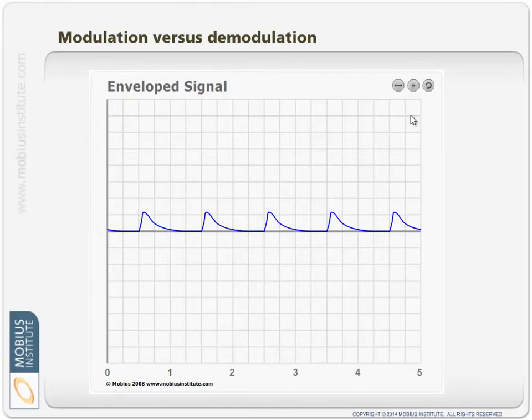It's because as those gears impact each other, if they were a bit worn or there was a crack or whatever, they also create this high frequency vibration. So again, I can use that enveloping technique to get rid of the low frequency, high amplitude vibration and just focus on what results when you get metal to metal contact. Same with broken rotor bars. You can see a situation with a broken rotor bar because of the crack that it creates this same stress wave, and you may pick that up, and there's other situations as well. But it doesn't rely on a modulated signal in the first place. It's just that we're generating stress waves or shock pulses, or we're exciting resonances in the accelerometer or the machine itself.